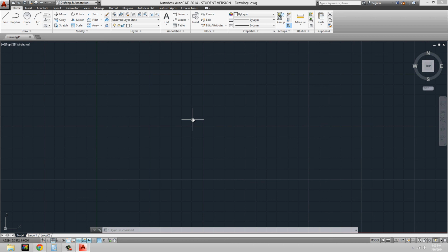Since it'll be required that we produce drawings that are to a scale, we need to start to enter precise values into the program. At this moment, there's a little bit of general background. The concept of drawing in AutoCAD is that we're drawing everything at full scale, that's 1-to-1. Unlike when drawing by hand, where you have to calculate the length of a particular line at a certain scale in advance, we're drawing everything as it would be in real life. Then the scaling happens when we bring our drawings in and work with paper space.